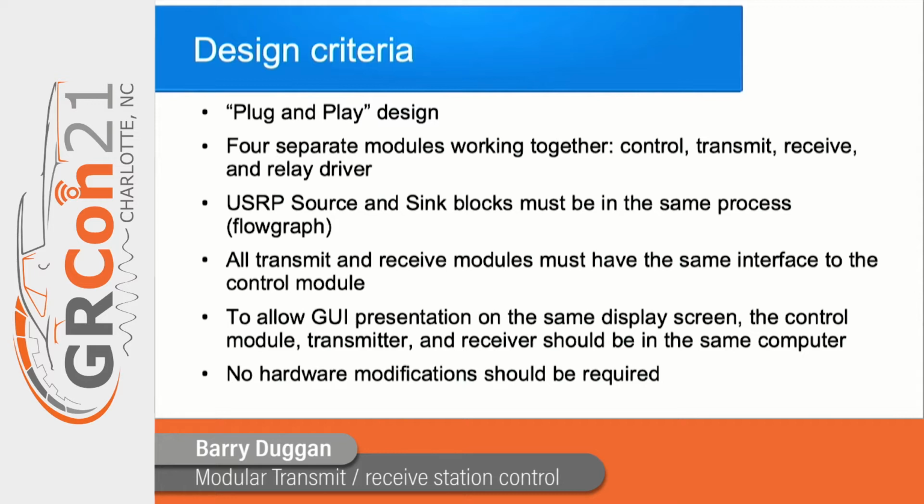My design criteria is that I wanted a plug and play setup where I could create different modules working together: a control, a transmit, a receive, and a relay driver. The USRP source and sink blocks must be in the same process for them to work, sharing the services, same flow graph.